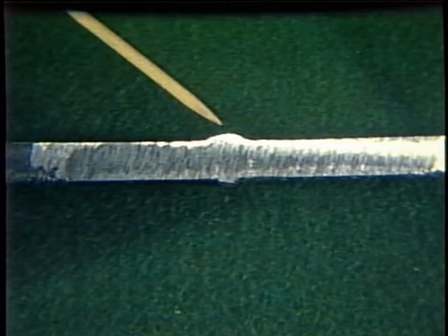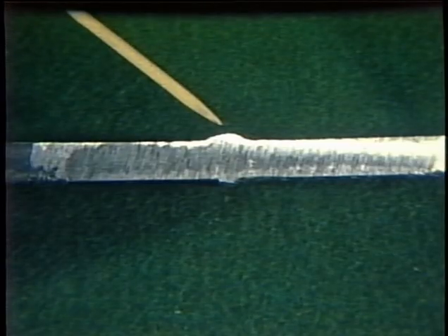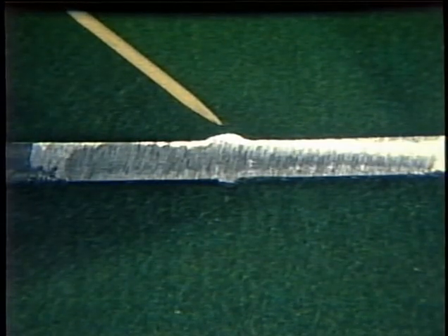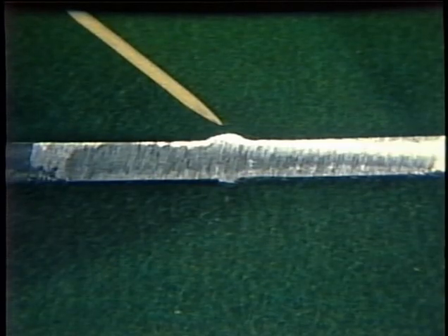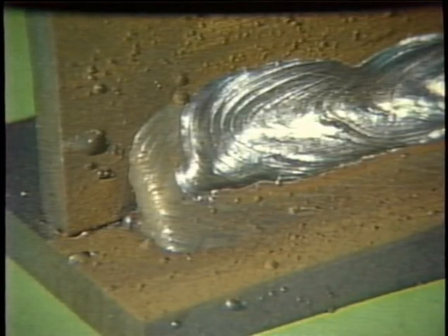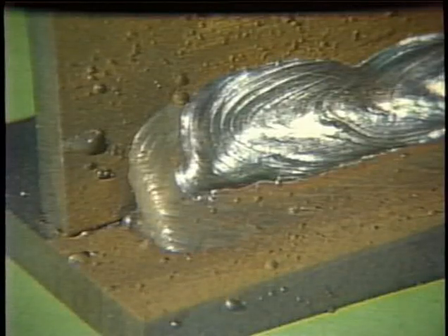When the plates are of unequal thickness, then the thickness of the thinner plate determines the size of the groove weld. A slight reinforcement is usually specified to ensure adequate joint penetration. It is sometimes believed that a high amount of reinforcement serves to increase the strength of the welded joint. This is not true. Not only is excessive reinforcement wasteful, but it also decreases the working strength of the joint due to concentration of stresses at the toes.